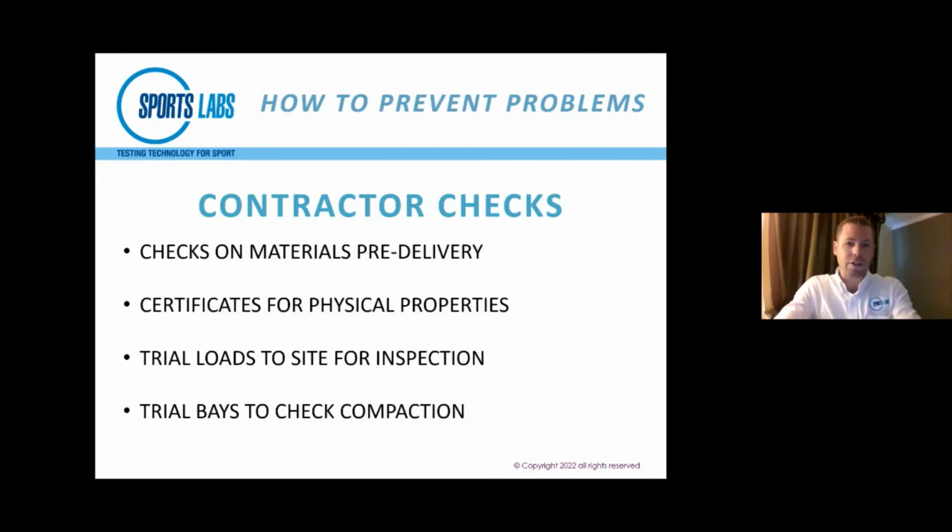It's good to specify that you do have a planarity to 10 millimeter tolerance, or a drainage rate of, you know, 25 inches an hour or something around there. And you can specify that, and we can hold everyone accountable, down to the general contractor or the subcontractors, to make that happen. That way, when we move on to the next stage, we know that specification has been satisfied.